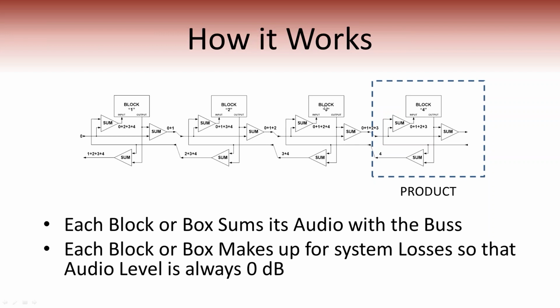The way this is accomplished is with line level 0 dB signals. In other words, this is like a summed broadcast network. We can send this stuff out to other products because it's all standard broadcast level. If you want to share this with a teleconferencing system, no problem. Just take the bus and send whatever you want out to that teleconferencing system.